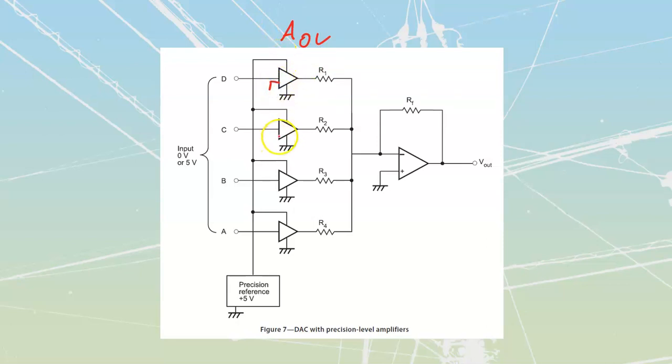The second line of these is just going to be tied down to ground for all of these over here. But anytime that I take any one of these and I put in a value, 4 volts, 5 volts, anything in that range, it's going to drive that thing hard into open loop amplification, and then it's just going to pass this precision 5 volts through. So that we've got 5 volts over here.